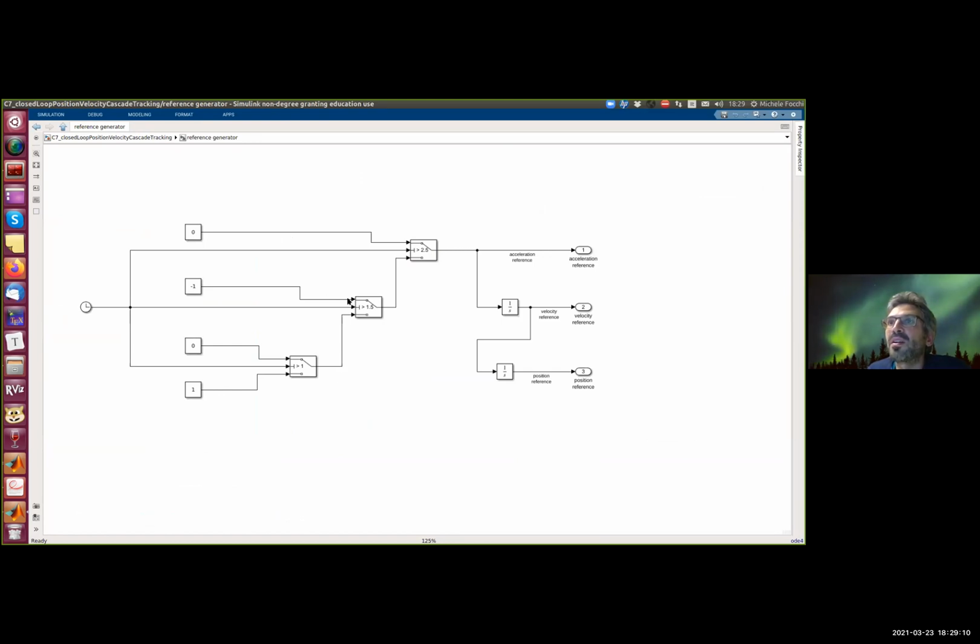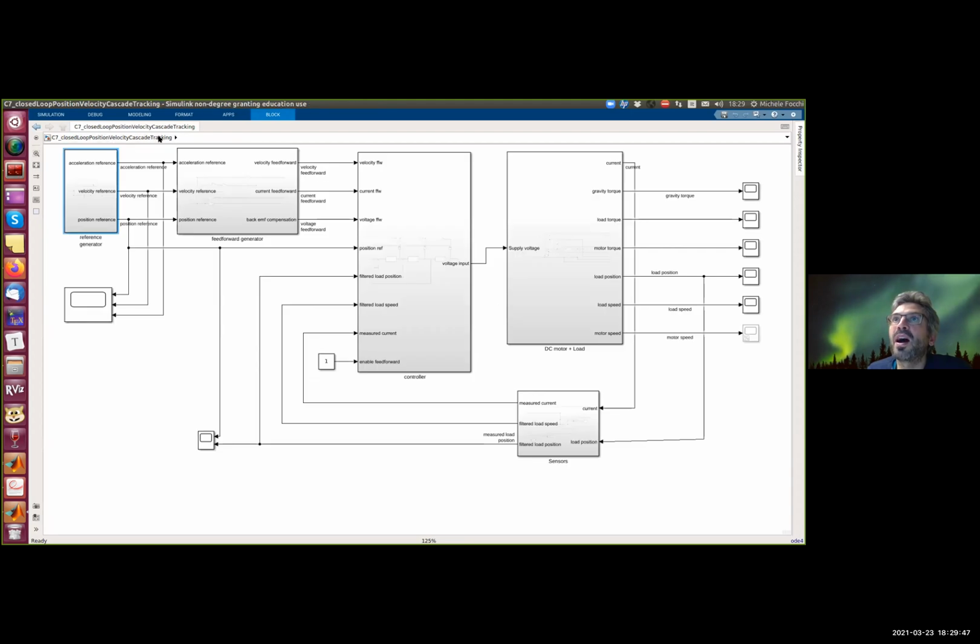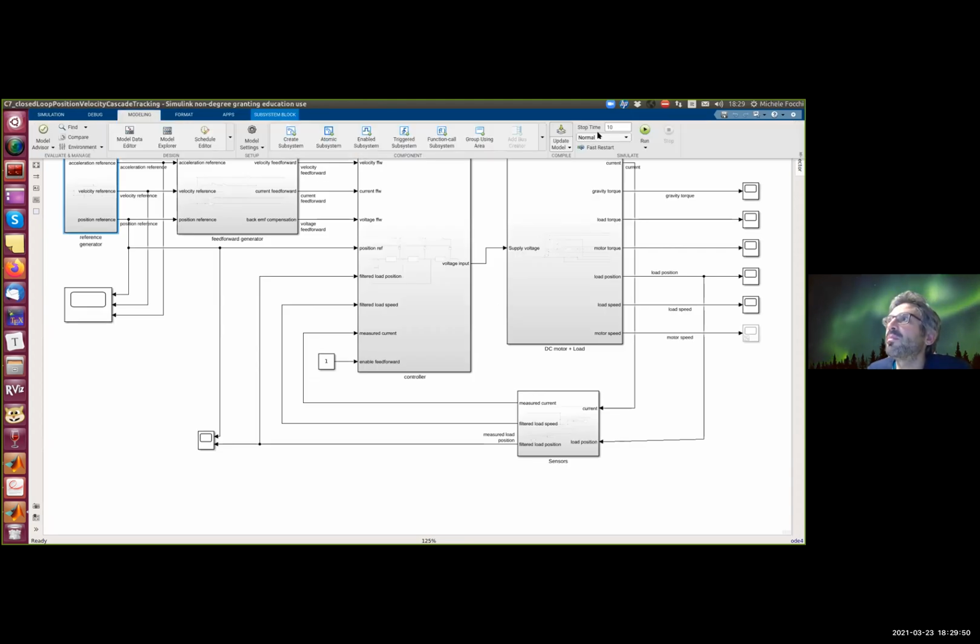Then here you go in this block. Whenever it's bigger than 1.5, it will start to decelerate, okay, giving -1 acceleration. And whenever the time becomes bigger than 2.5, it will provide 0 acceleration. And this is the acceleration that has a shape something like before: positive, then 0, and then negative. The integral of this is the velocity reference, and the integral of the velocity is the position reference. So let's look, how do they look? We just try to simulate them.